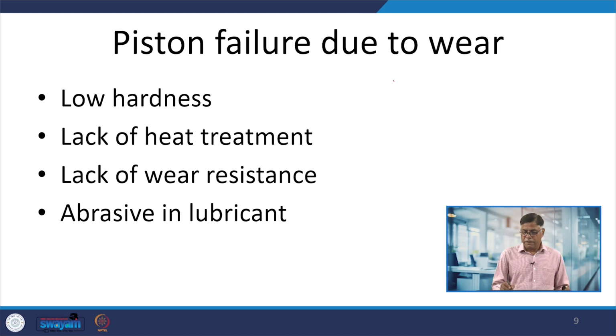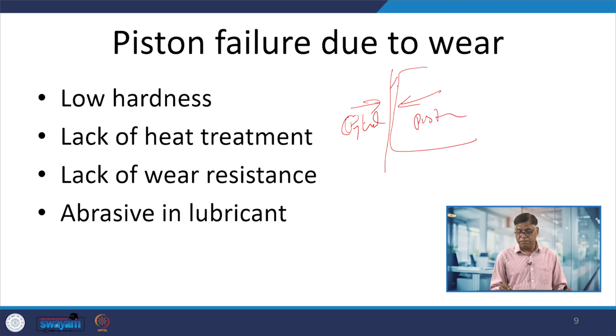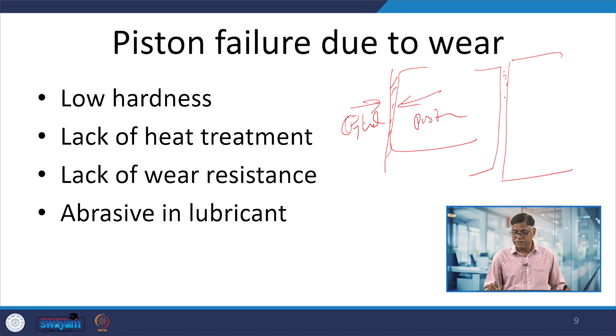What happens when there is no lubrication? There is a direct contact between the cylinder and piston. And if the piston and the cylinder are interacting directly, then there will be too much metal to metal contact, leading to the accelerated adhesive wear. So, presence of the lubricant in between the cylinder and the piston, what will it be doing? The presence of lubricant will be reducing the direct metal to metal contact, and facilitate reducing the friction and facilitating the smooth operation with very less wear.